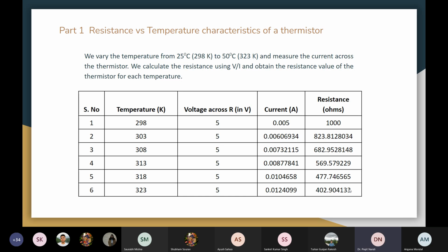What typically people just end up doing is just looking at the voltage profiles and saying that things are okay. Of course, we look at that as much as possible, but it is very important to actually look at the current profile, the current values flowing through the elements, and ensure that none of the current values are funny, meaning none of them falls in an unreasonable range of becoming too high or too low. So that is a very important practice as circuit designers or electronic system engineers.